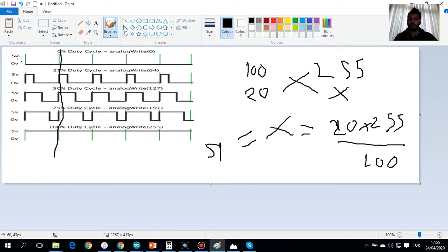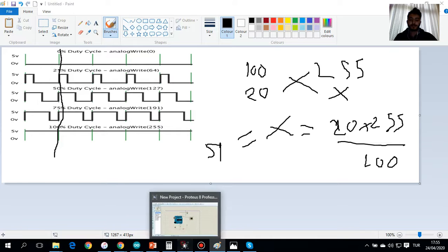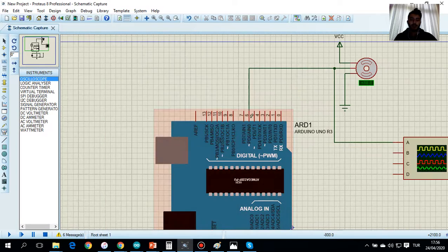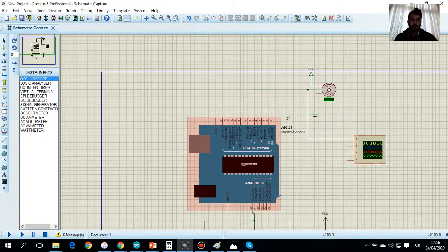How are we going to use a duty cycle here? We'll drive a servo motor here, guys, with the PWM signal. As you see, it is connected to pin 6 because it is marked as a PWM pin, a PWM module pin. You can also use pin 5, pin 3. These pins, port B1, port B2, and port B3, can be used as a PWM module.